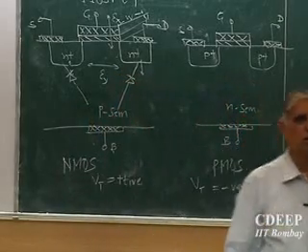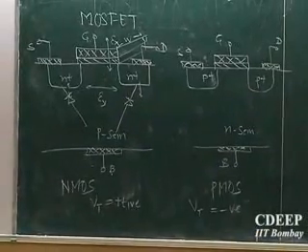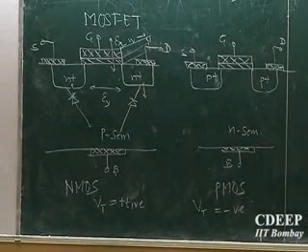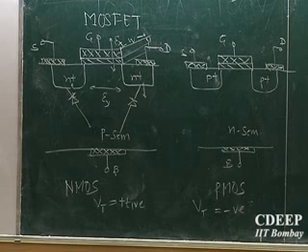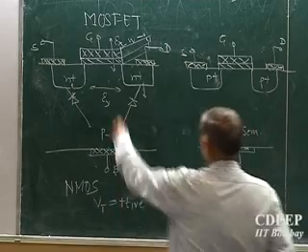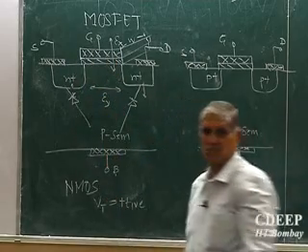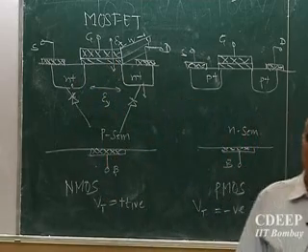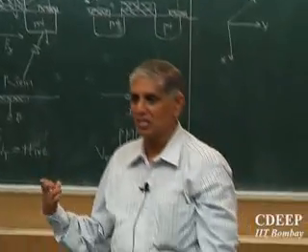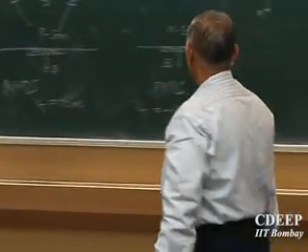So we have two diodes sitting inside this substrate, one from source to the ground, or source to the bulk, and the other from drain to the bulk, and then there is a field effect capacitor which is sitting in the center. Okay. So that PN junction is a little bit required here because there is a junction going on.